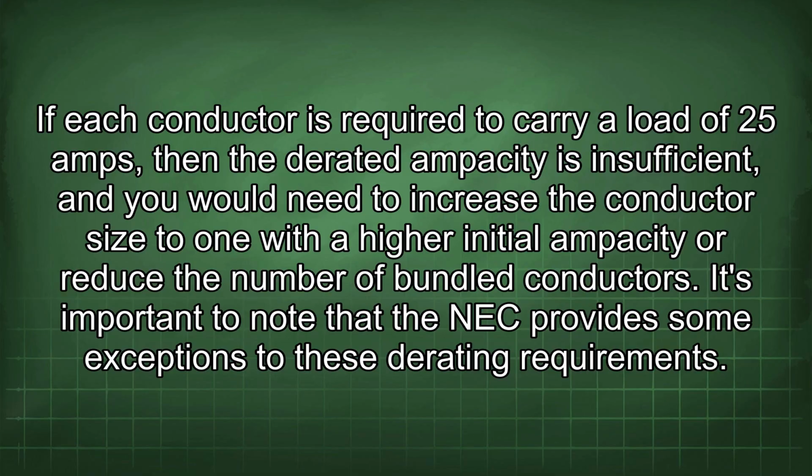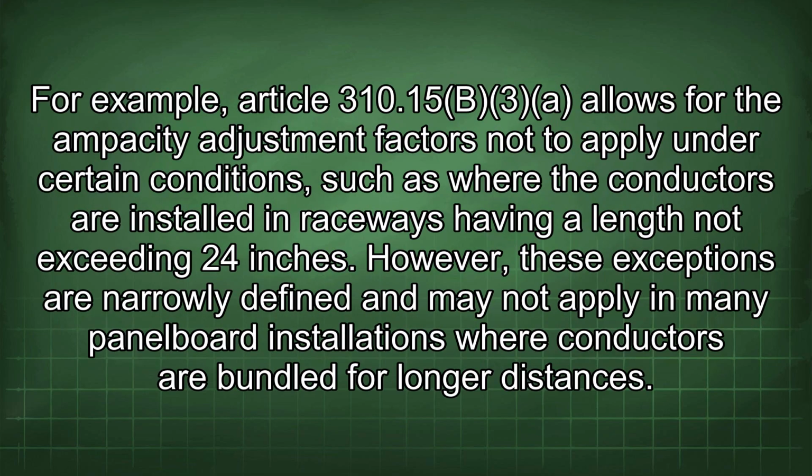conductors. It's important to note that the NEC provides some exceptions to these derating requirements. For example, Article 310.15(B)(3) allows for the ampacity adjustment factors not to apply under certain conditions, such as where the conductors are installed in raceways having a length not exceeding 24 inches. However, these exceptions are narrowly defined and may not apply in many panelboard installations where conductors are bundled for longer